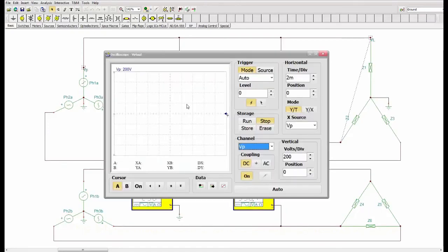Okay, I have the oscilloscope set up in the TINA simulator. To do that, I needed to insert some outputs, as they're known. Okay, so tell the oscilloscope where to make measurements. So VP output I've placed from this point to this point. VP is V phase, of course, and VL or V line goes from that point to that point. Okay, so between two lines.